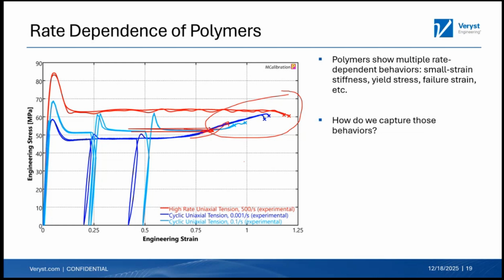So for an impact application, again, if we're just talking about stress versus strain, I'll do 3. Clients will ask for 5 sometimes. I'll do it. I don't think there's a lot more value there, but I'm happy to do it. I don't like to do less than 3, because when we do 2 and you've got a difference between the 2 tests, which one's right? You don't know. You have to run a 3rd test to understand if one was right or one was wrong. ASTM standards typically say 5. We say 3 are plenty.